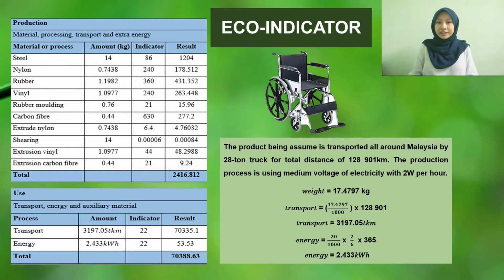For eco-indicator, it divides into 3 categories which are production phase, use phase and disposal phase. In the production phase, all material and process that we get from process 3 will be analysed using the relevant eco-indicator value, and then we calculate the result by multiplying the amount of weight with the indicator value. The result of the indicator represents the load of environmental impact.